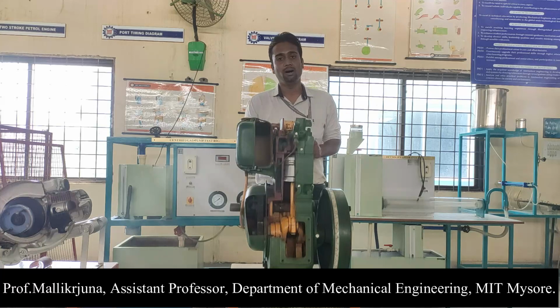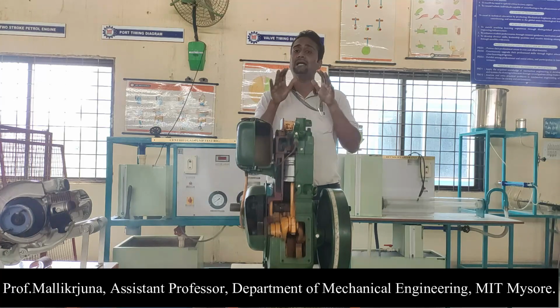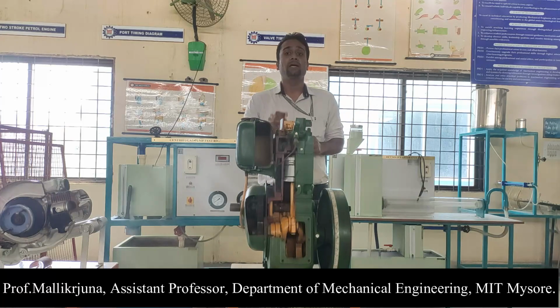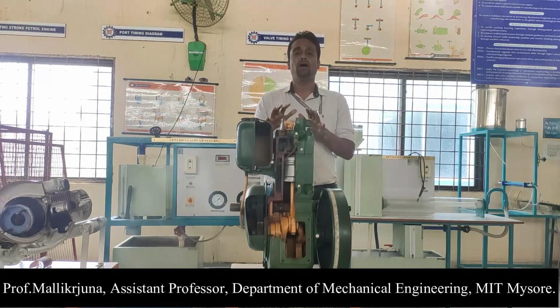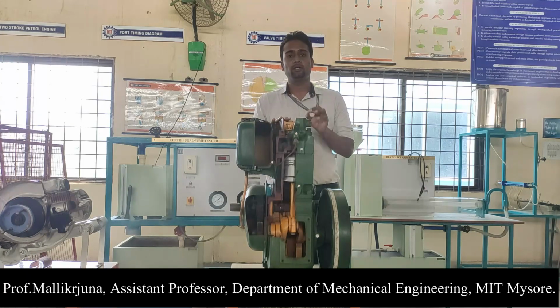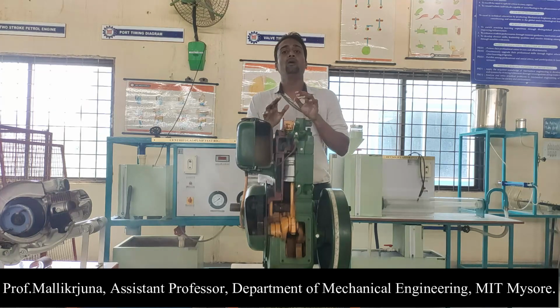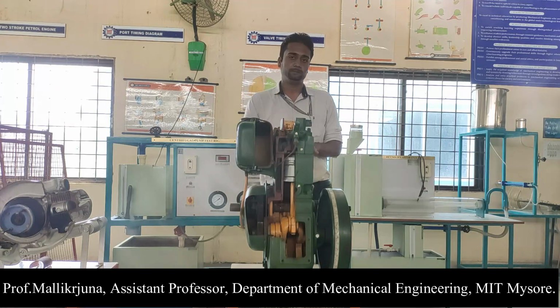So this is how we express the position of the piston with respect to the cylinder at various strokes. But practically this will not happen. What I mean to say is, exactly at the dead centers, the valves are not going to open and the valves are not going to close. In order to look into those precise values of valve opening and closing, we are performing this particular experiment. So what is our aim in this experiment? To precisely look into the valve timing, I mean valve opening as well as valve closing, for various operations that are involved in the 4-stroke engine. So now let us conduct the experiment.